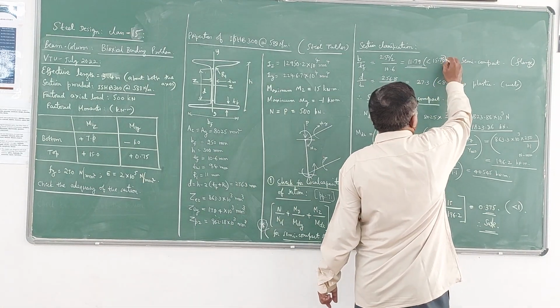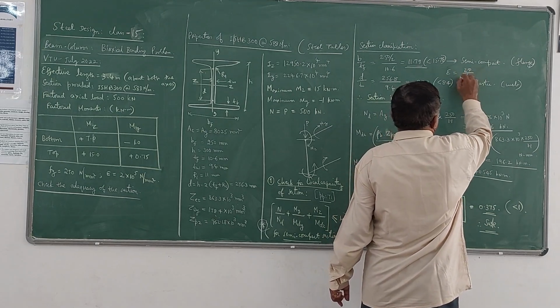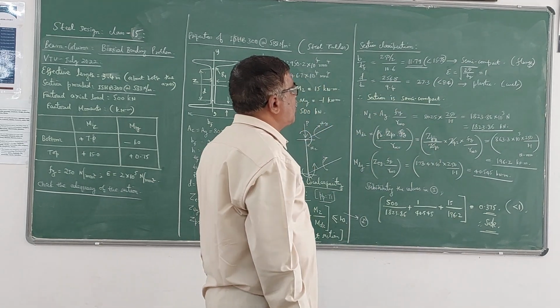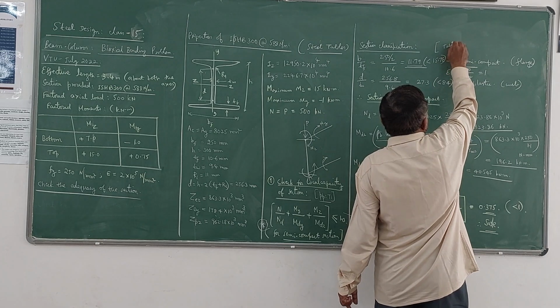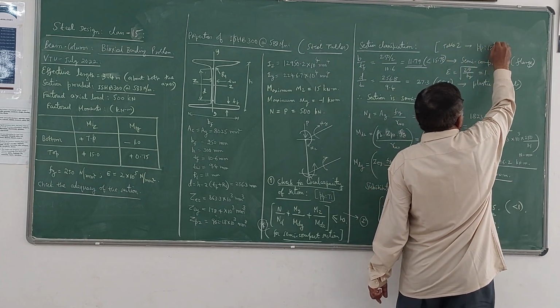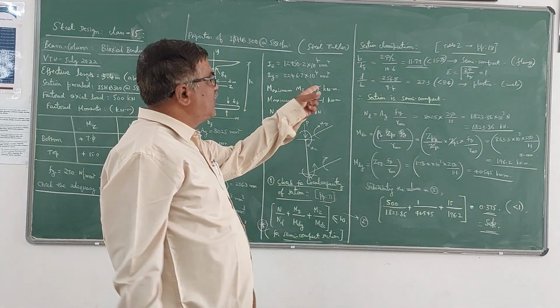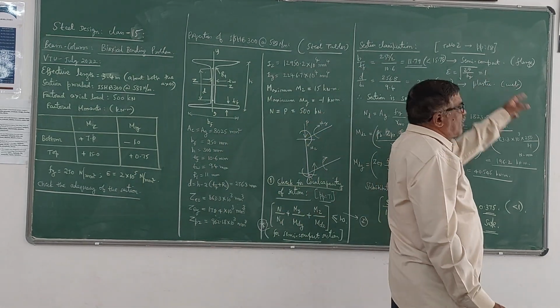Epsilon is 1 here because epsilon is the root of 250 divided by Fy. Here Fy is 250 itself, therefore it becomes 1. So it is a semi-compact section. You can refer to Table 2, which is on page 18 of the code. So you know how to classify the sections. Since that value is less than 15.7, of course it becomes a semi-compact section.